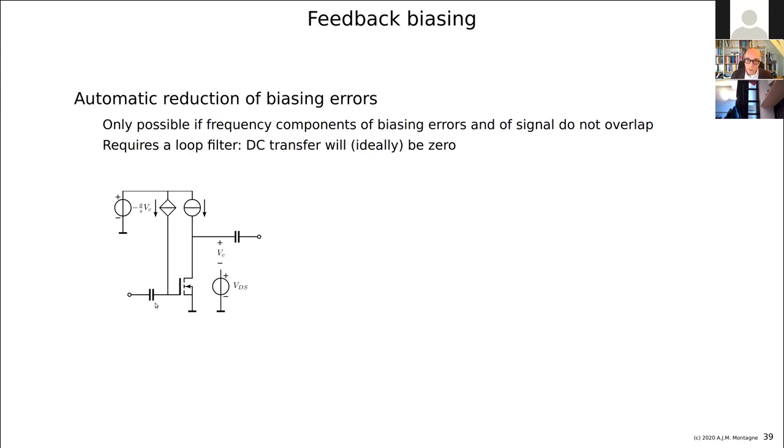But if you would connect this to the source and this to the load, you already have a system with 3 poles, because there would be 1 capacitor, a second capacitor, and here an integrating transfer. So stability has been dealt with. We have discussed such a circuit with operational amplifiers in the bachelor course, and that is in the homologation program. So this is a way of fixing the DC voltage at the drain by making a loop with this voltage. Of course, you can do another with this current, sorry.